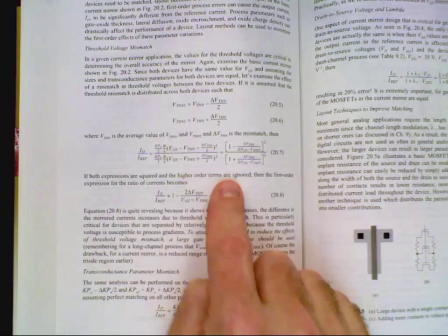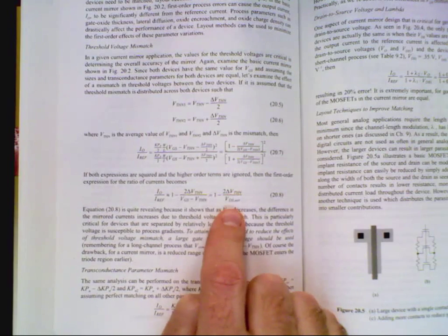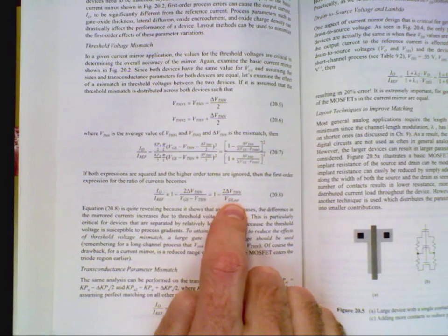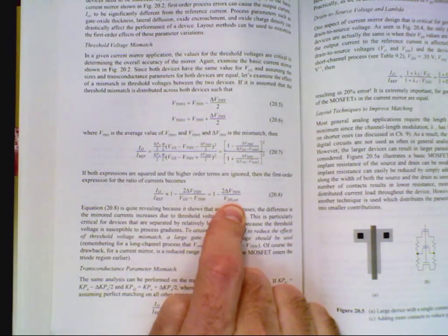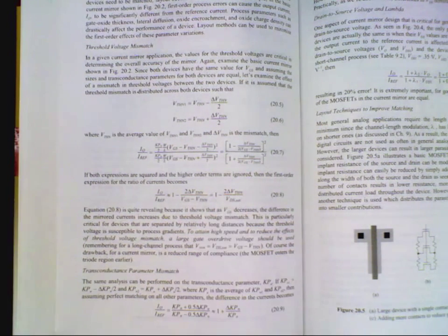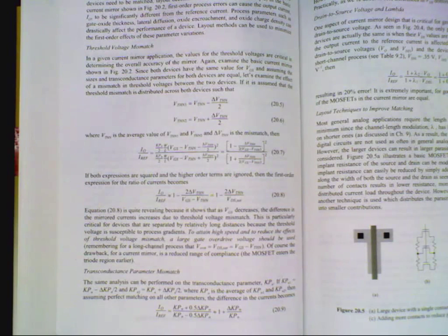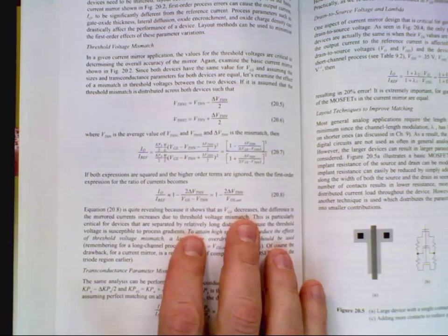If that's varying, ideally it's 0, so it doesn't matter, then your VDS sat, which we also know is VGS minus V threshold N, or V overdrive or V excess, would need to be really big, and then we would get good matching and high speed by using large VGS, and the drawback would be not as large output swing because the devices would go into triode faster, all right? So you can see the derivation there.